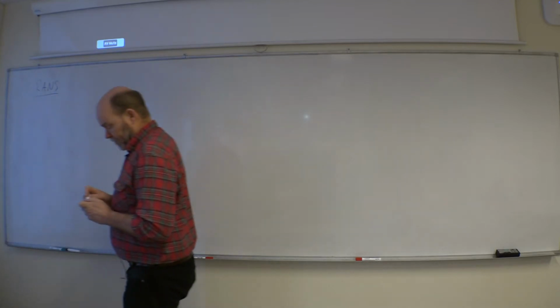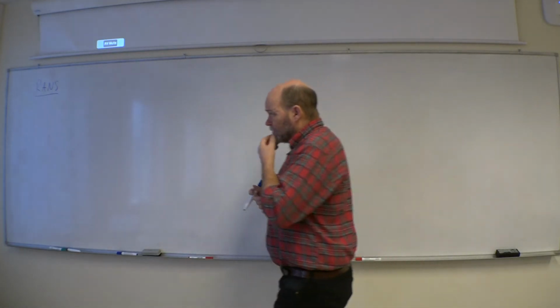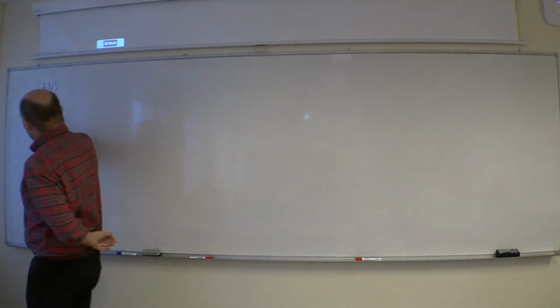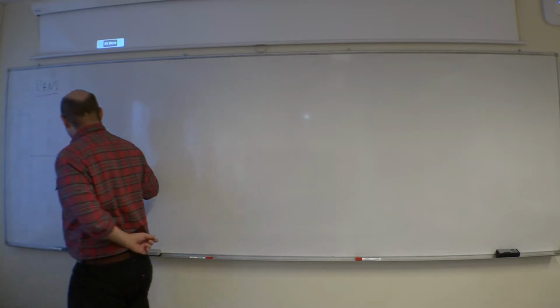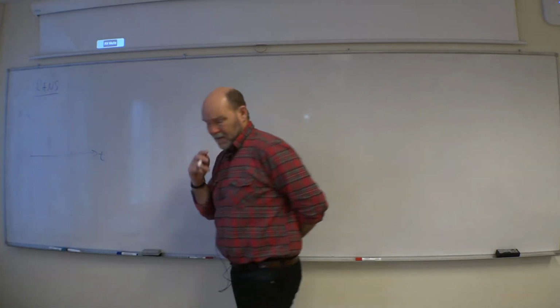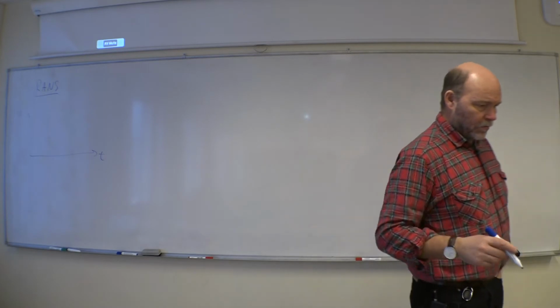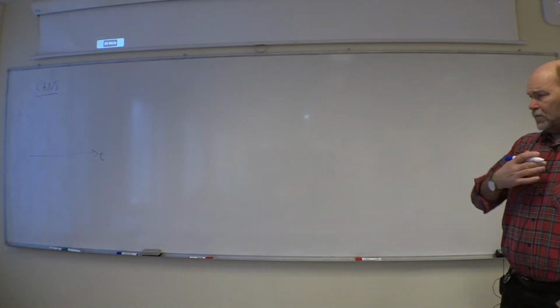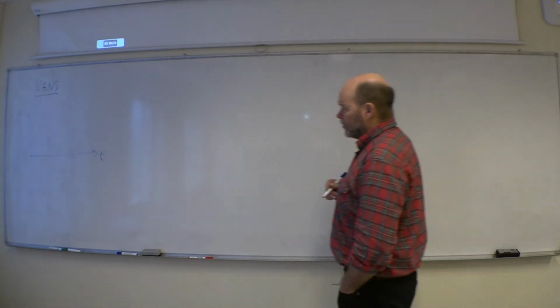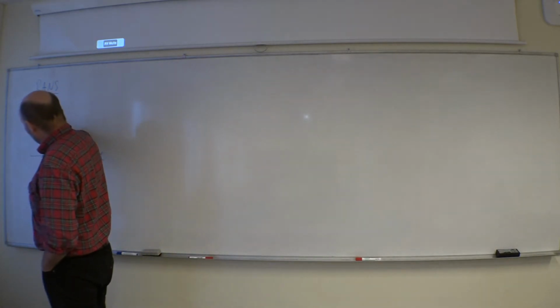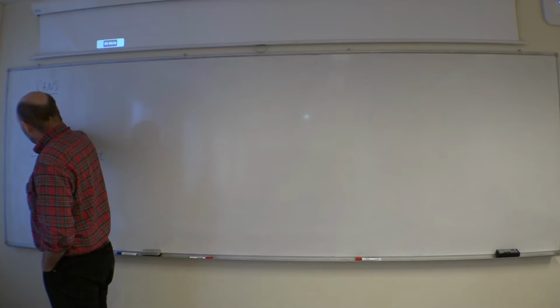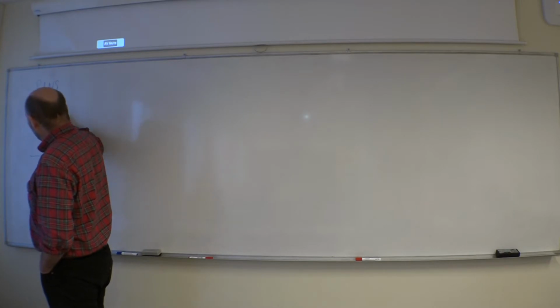How to find the Reynolds-averaged Navier-Stokes. If you look at a turbulent signal, say velocity as a function of time, imagine you have a probe at one point inside the flow, measuring the velocity with a very good measuring system, and you will have a signal looking something like this.